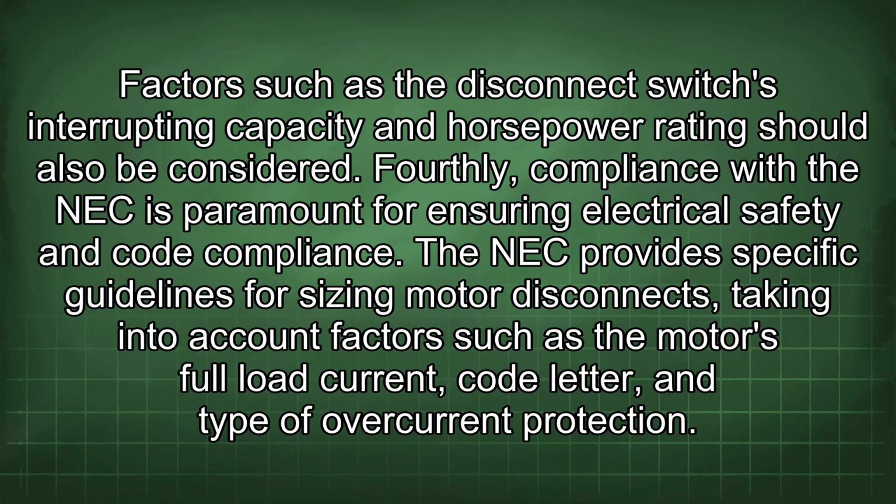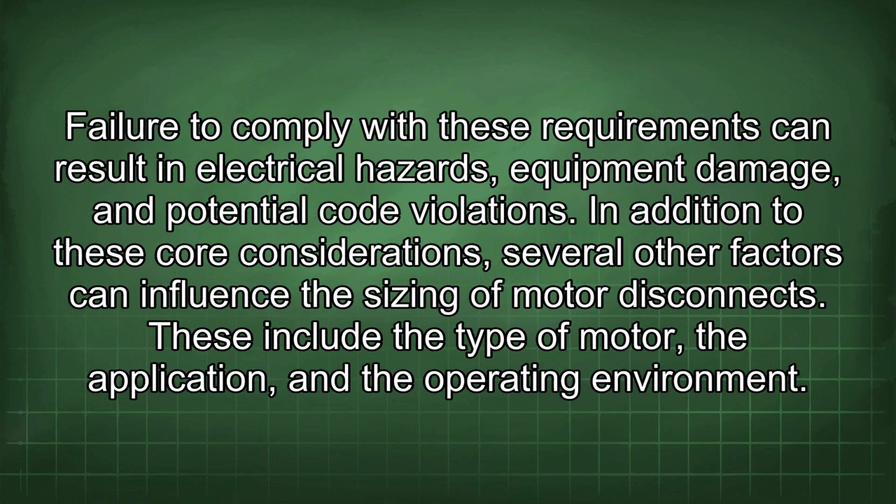Fourthly, compliance with the NEC is paramount for ensuring electrical safety and code compliance. The NEC provides specific guidelines for sizing motor disconnects, taking into account factors such as the motor's full load current, code letter, and type of overcurrent protection. Failure to comply with these requirements can result in electrical hazards, equipment damage, and potential code violations.